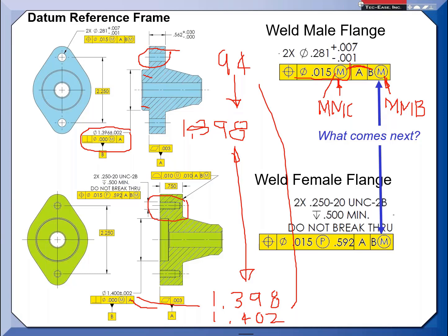If you were to build a hard gauge, it automatically builds this right into the gauge. What we call datum shift, datum displacement. So really it's about what size the datum feature is. Also, I've got to say this: the features are very perpendicular. They're not tilting. They're very perpendicular to the primary datum. In other words, nice planar. Small diameter, very perpendicular. Big hole, very perpendicular.